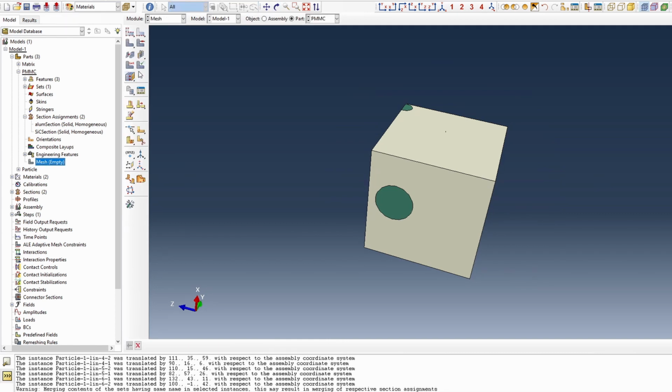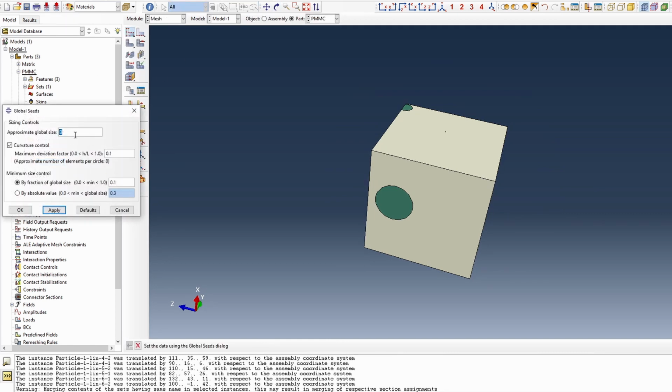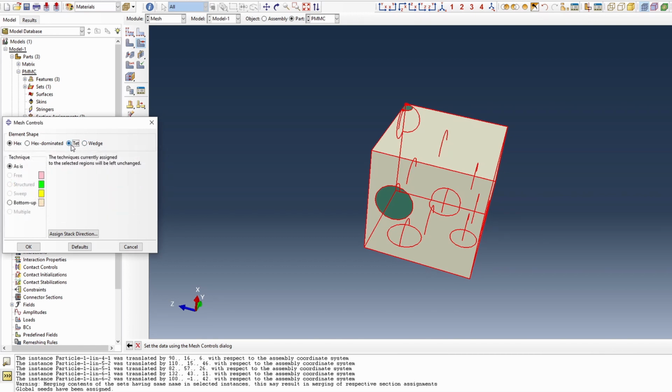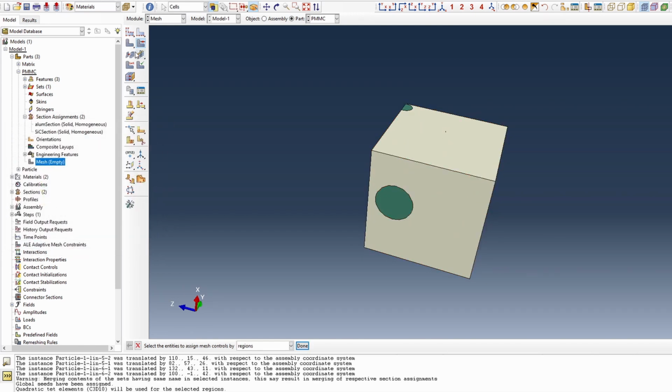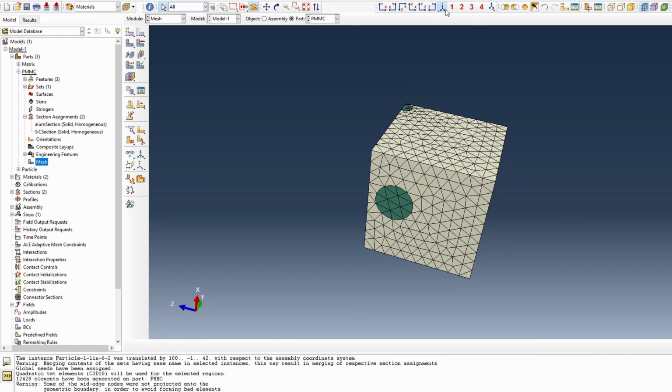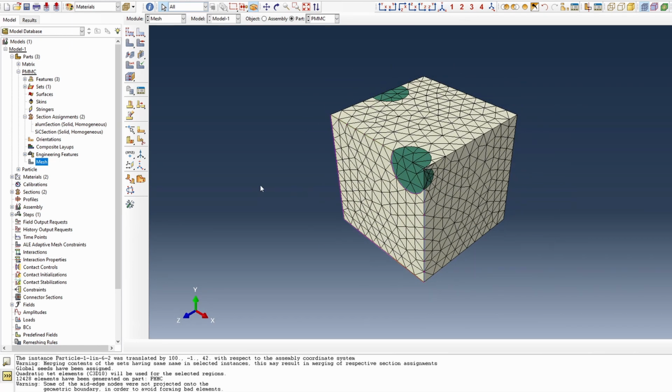So we can then mesh. It's recommending 3, but let me probably double that just to make sure that I have a sizable mesh that will converge very quickly, and then we can get this done. So I'll use a tetrahedron to mesh it, so everything is meshed in the form of a tetrahedron. So we've got that.